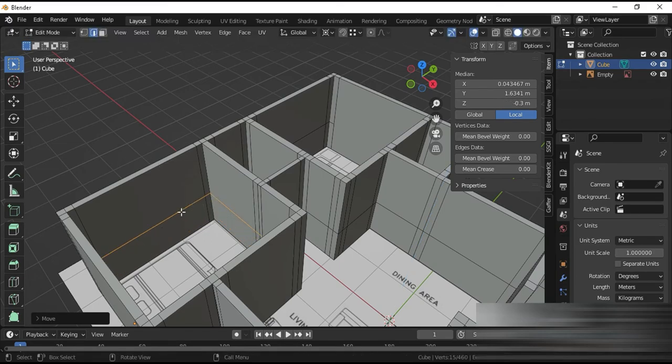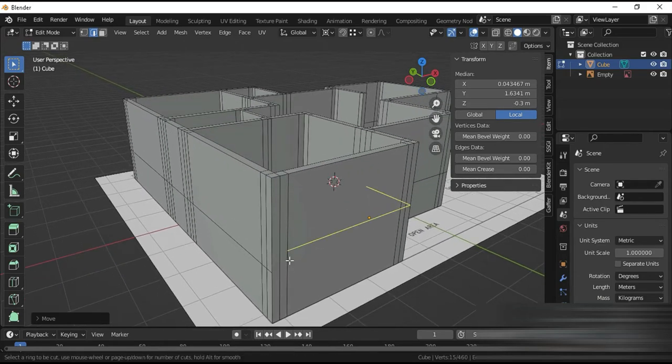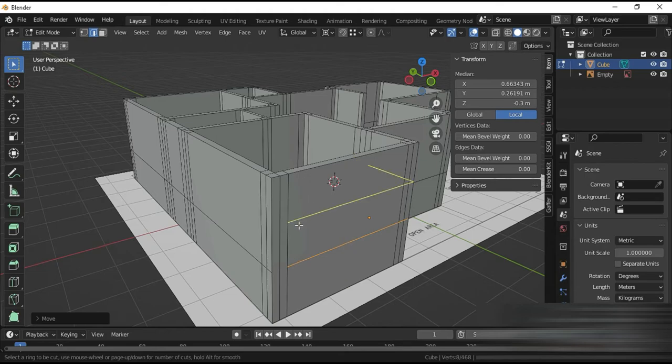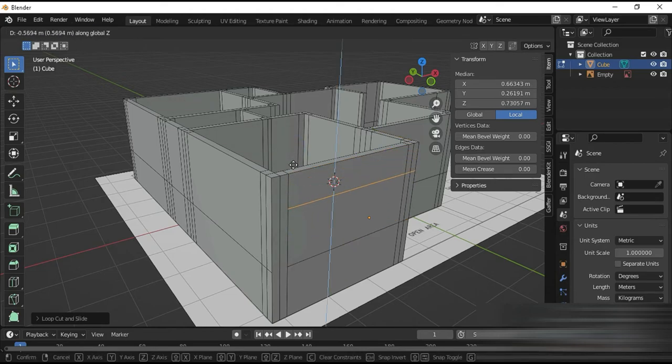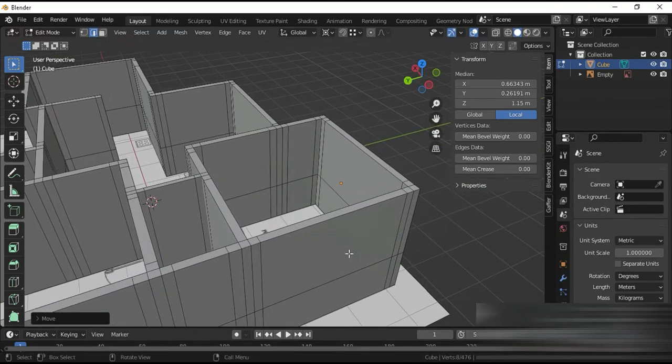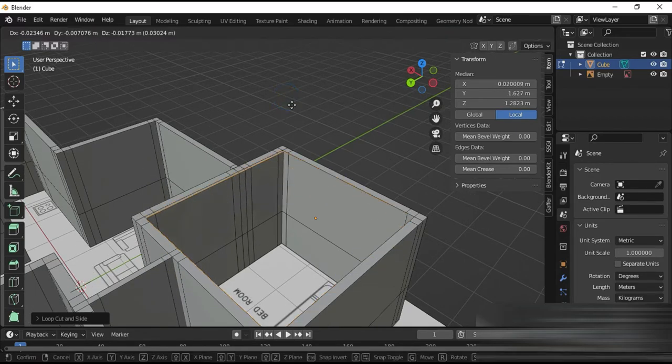And for the above, we also have to set a limit. So Control and R, down, and G and Z, 1 meter is done. And for the above, it's going to be Control and R, up, and G Z, minus 0.15, finished. So the workflow is the same now. We have to do it for all of them. So Control and R, up, G Z, minus 0.15.